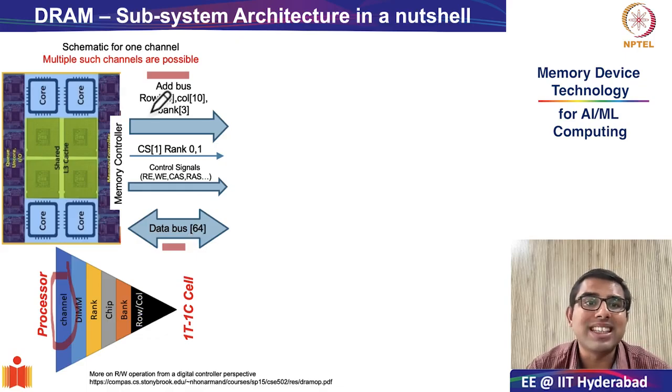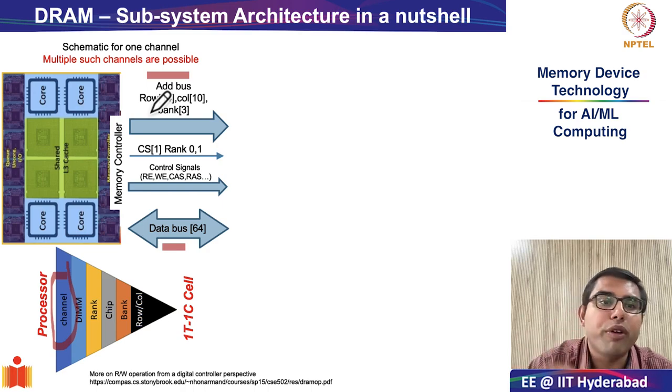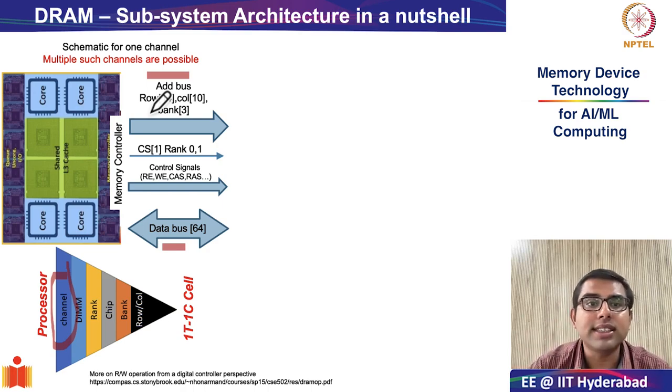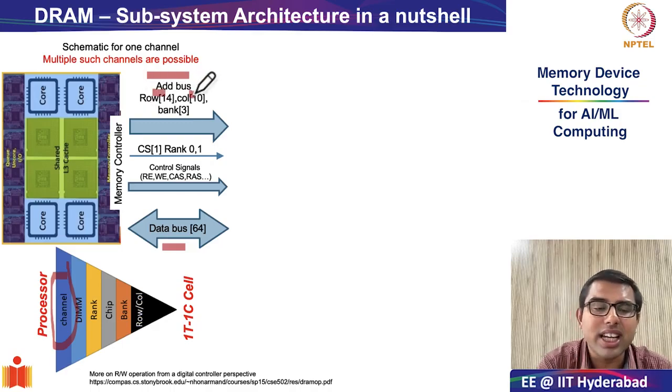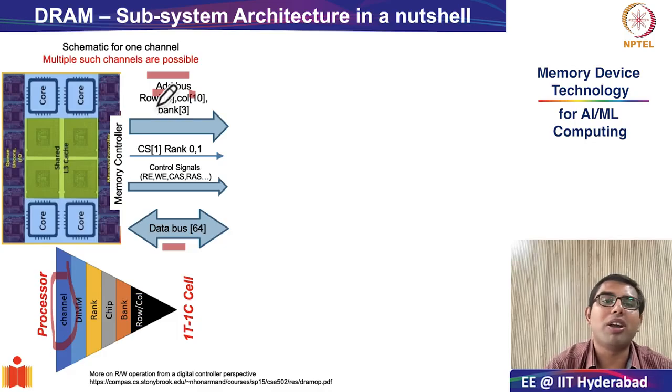The address bus consists of 3 main components, because it is supposed to bring out data from memory locations, which requires 3 different aspects of address. The first is definitely the row and the column address. As you know, the address bus will reach each and every memory array, and like we discussed in the last class, from every memory array only one bit gets selected. The row and column from which that one bit comes out of each memory array is indicated by this row and column address.